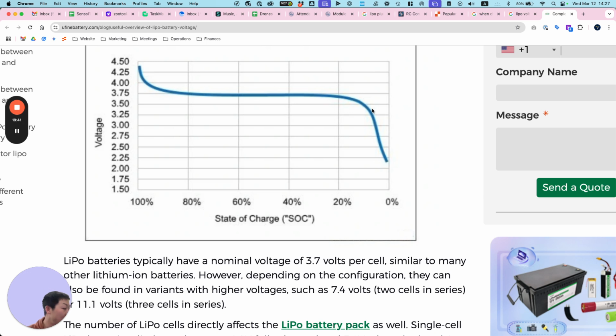And there's ways to monitor it. Even though we don't have a meter on here, you can get a meter like this one, and then you can keep reading the voltage as you're using it. And there's other meters that will actually send an audible alarm if any of the cells drop below a certain threshold. That way you don't keep it plugged in and keep draining the battery. So we lost a couple batteries that way. Let's not lose any this semester. And that's just keeping an eye on the voltage.